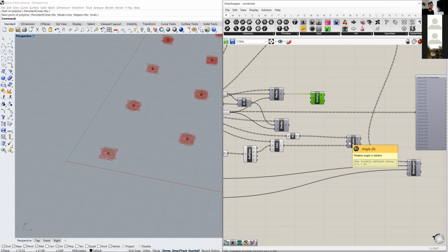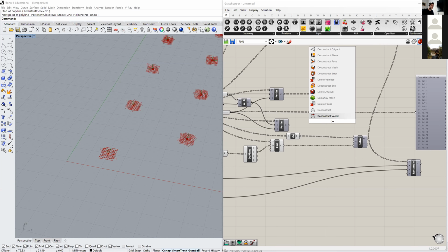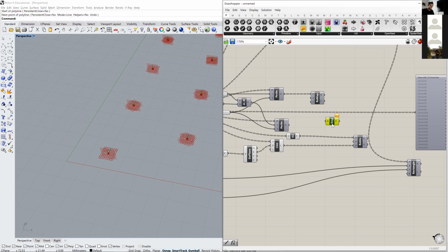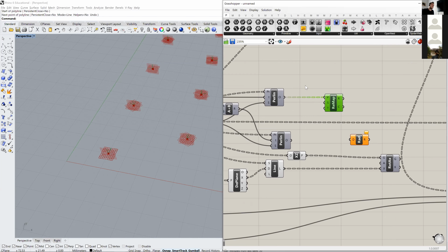By default, all the rotations, all the angular calculations in Grasshopper are counted in radians. I'm not able to do these calculations in radians very quickly, so I'm always recalculating into degrees. So I need a degrees input to transform into radians, and I will be remapping the values of the Perlin noise, which is,